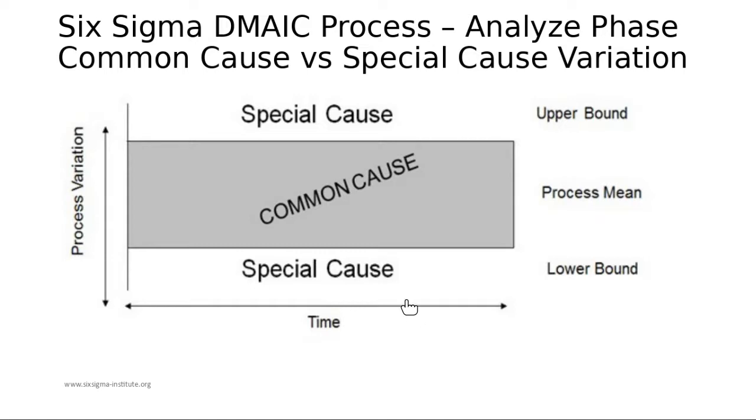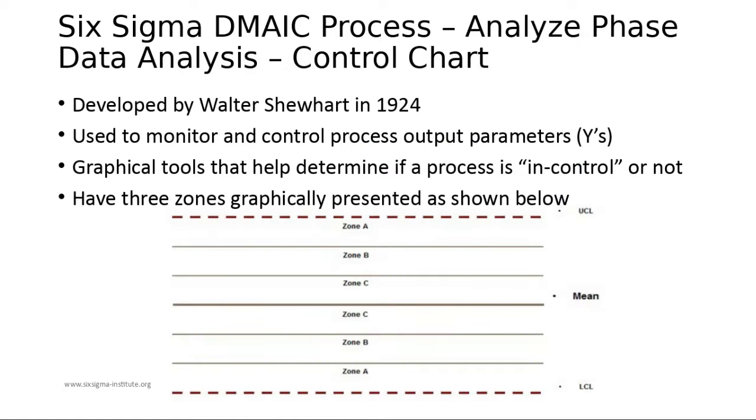There is a difference between control limits and specification limits. The control chart shows the control limits. The specification limits are usually determined to be outside the control limits. Otherwise, if you are exceeding the specification, then you will be exceeding the control limits. That's why your specification limits have to be within what a capable process can produce.